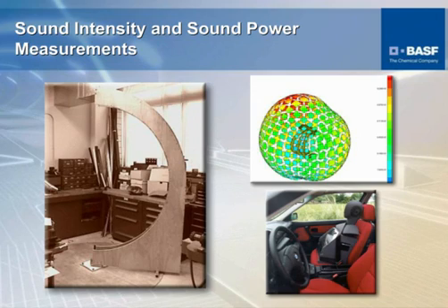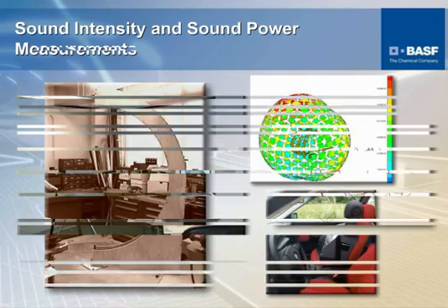Another testing tool is basically to look at the acoustical parameters by creating a structure that you can rotate 360 degrees around a source or a noise source, such as the intake manifold here, and then we can extract the parameters from the sound pressure level or sound intensity by rotating that structure 360 degrees at a 5-degree increment or more.